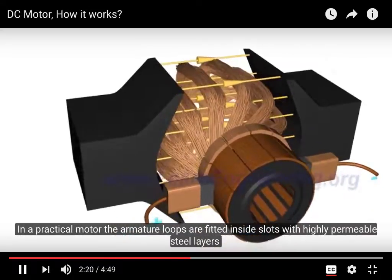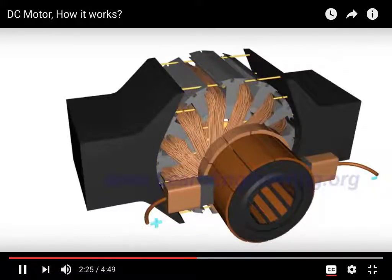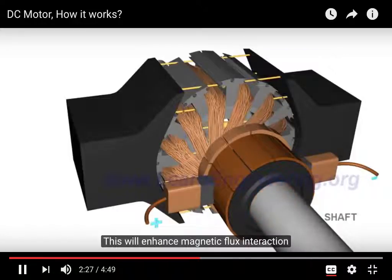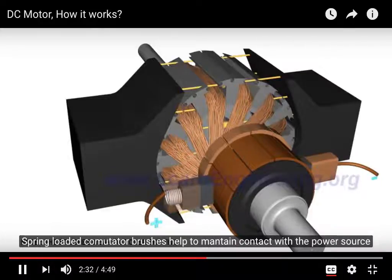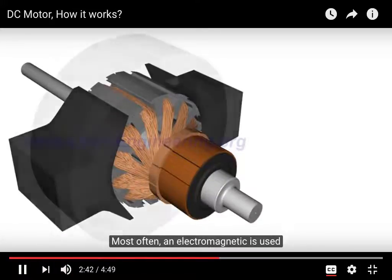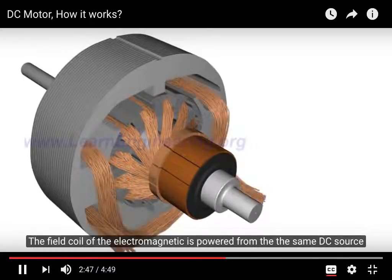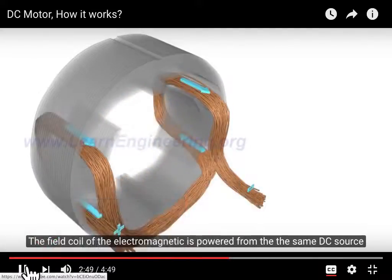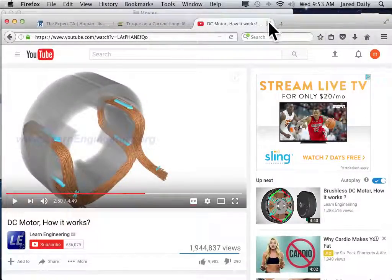In a practical motor, the armature loops are fitted inside slots of highly permeable steel layers. This will enhance magnetic flux interaction. Spring-loaded commutator brushes help maintain contact with the power source. A permanent magnet stator pole is used only for very small DC motors. Most often, an electromagnet is used. The field coil of an electromagnet is powered from the same DC source. Okay, so that's good enough for now. And you get the idea of how these things work.